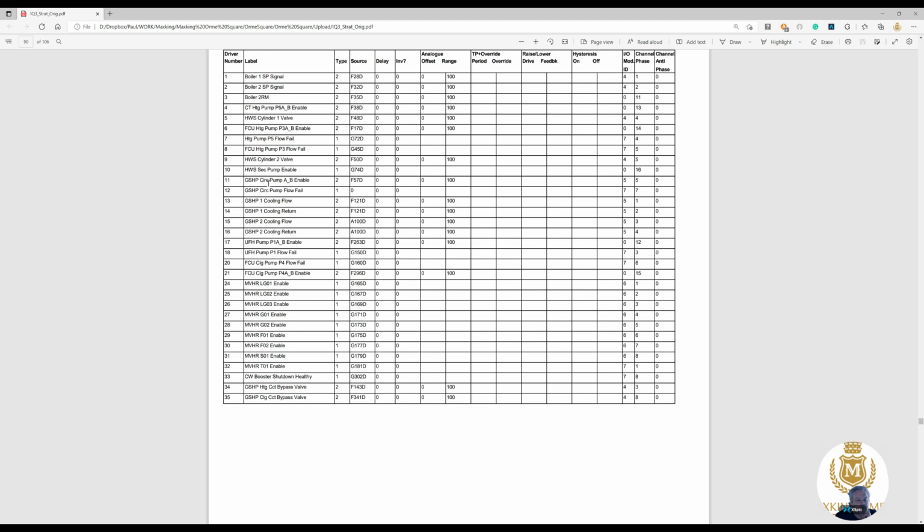Maybe it sends a light, puts a light on the panel, which if that's the case, I've got to have that as well. So DL1 is going to be the light, circ pump flow fail. Yeah, must be. Let's write that down. Right, then let's look at these DIX modules.